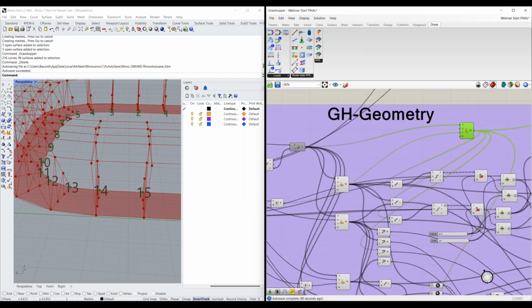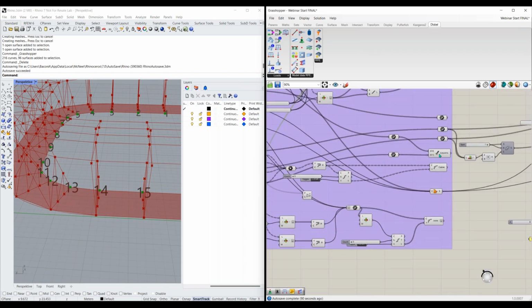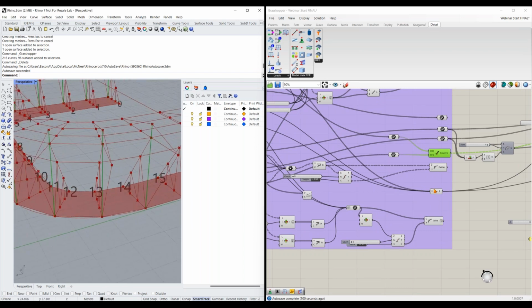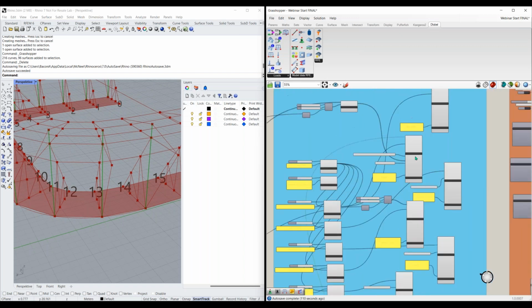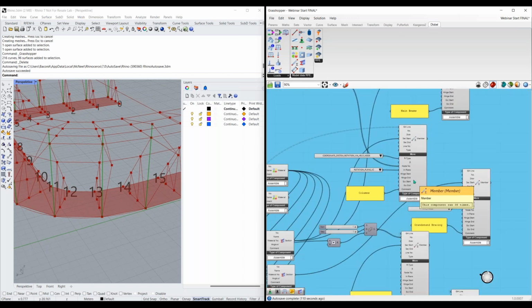And then if I click on, you can see for my columns, these are all the columns that I'm referencing. And so now the strong axes of my columns are going to be in the correct rotation, even if they're going along this curve here, because I'm referencing these help nodes. So that is the benefit of using help nodes in your model data here.